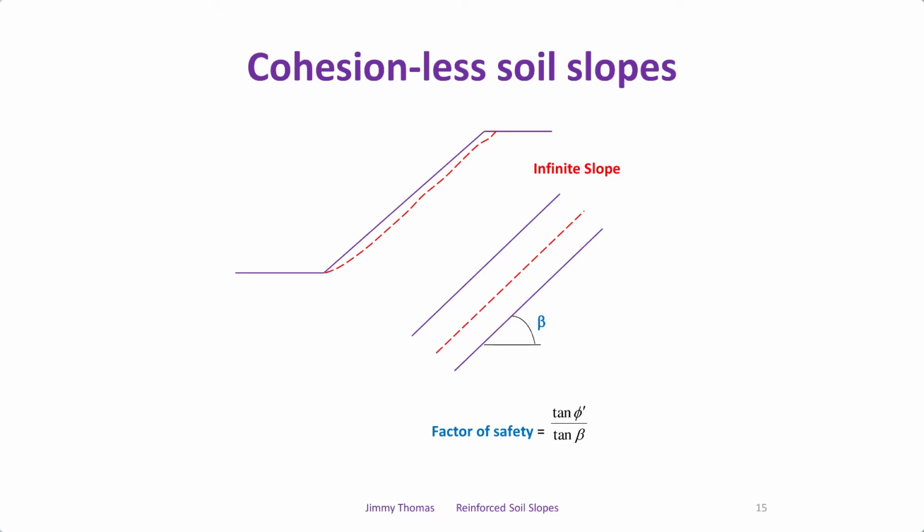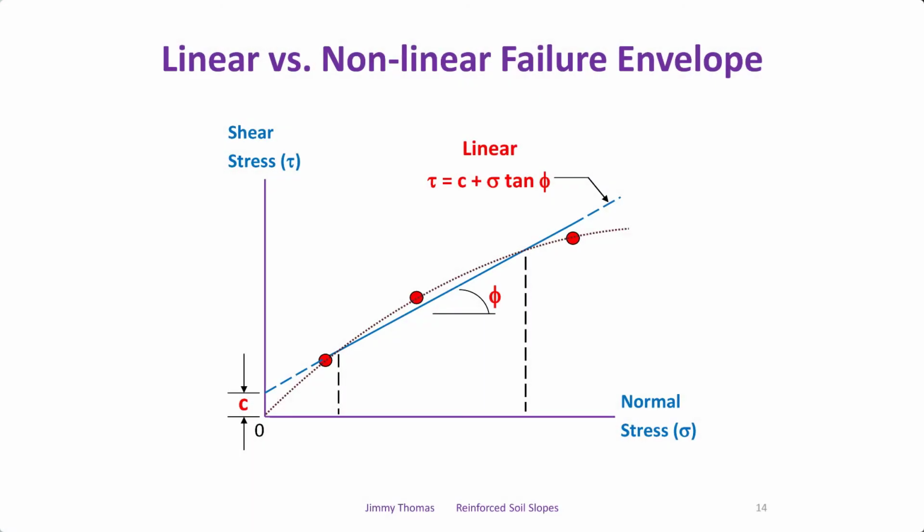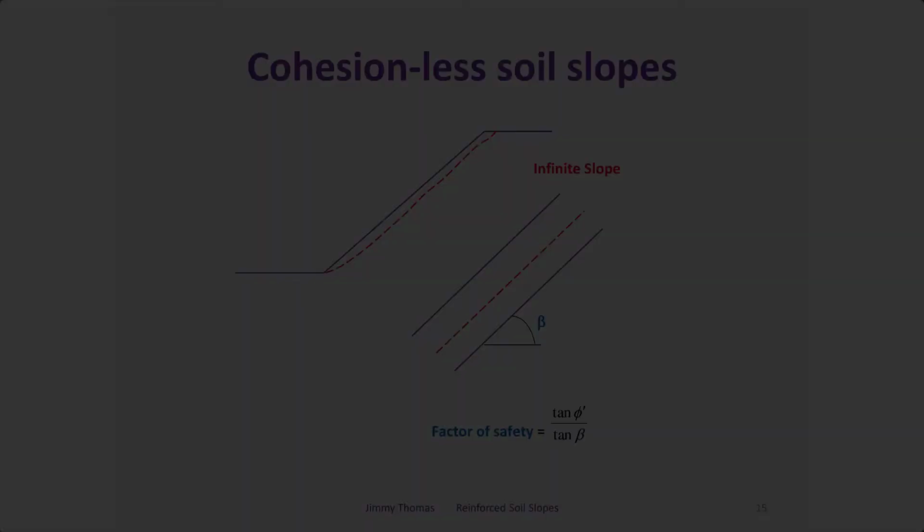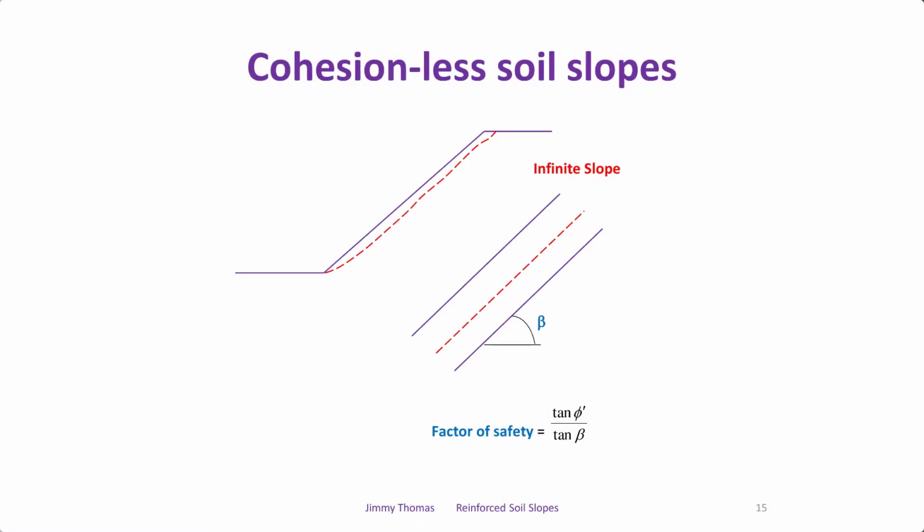It can fail that way. So what are the stresses here, the vertical stresses? They are very, very low. And what is my shear strength? If I take the straight line equation, I over predict my strength, so it gives me a higher factor of safety. So this is another part of the c and phi business.